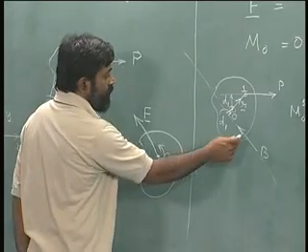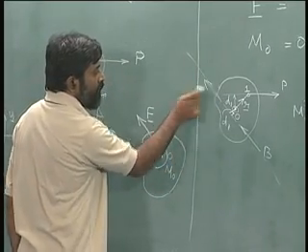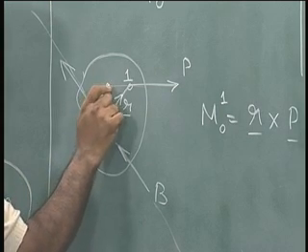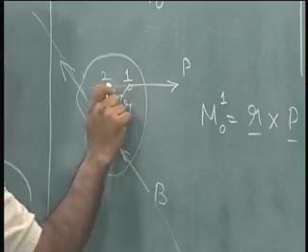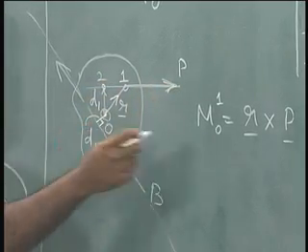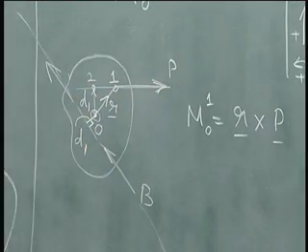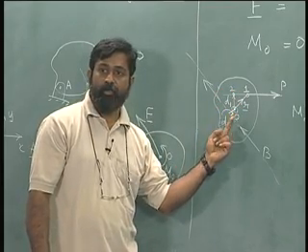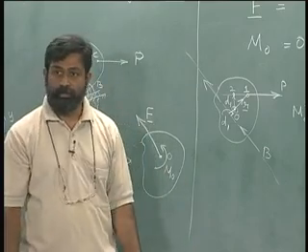Remember, whether the force is over here or the force is over here, the moment of this force about O will remain the same, okay. So even if I had put the force over here, let us say this point is 2, I would have gotten the same moment, okay. So it is only the perpendicular distance of the force at a part with respect to a particular point that is important to us, okay.